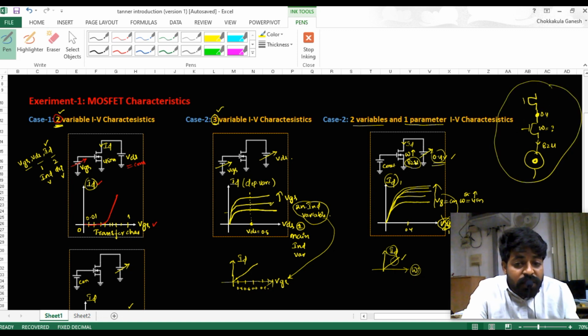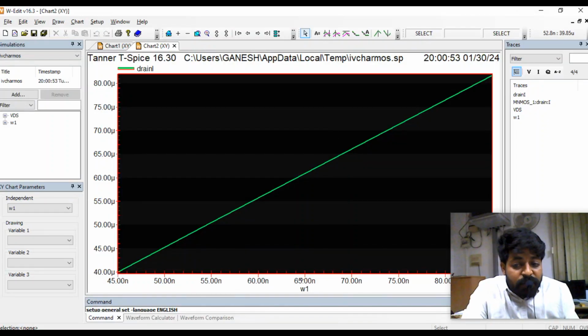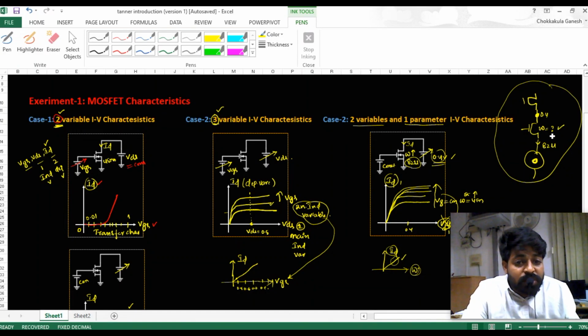You have to do this kind of simulation. So keeping that 0.4 and doing the sweep analysis for this transistor, you will be identifying the transistor current of this much for the value of W, showing the dependency of the drain current on the W. So this graph easily gives the conclusion where you need the complex circuit design analysis, where the W value sizing, and for complex circuit design, everything will be made very easy, right? When you do this kind of simulation, when you know this kind of simulation.